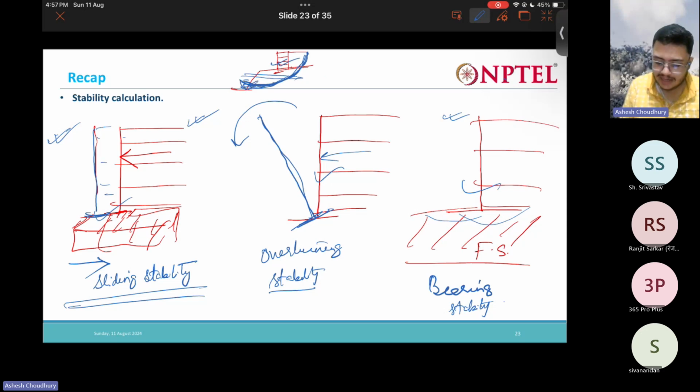If the slip circle failure check is not satisfied, even though all the other checks are satisfied, the whole structure is going to come out with the failure of the slope. So we need to consider this mostly when we are constructing the reinforced soil wall on steep slopes.